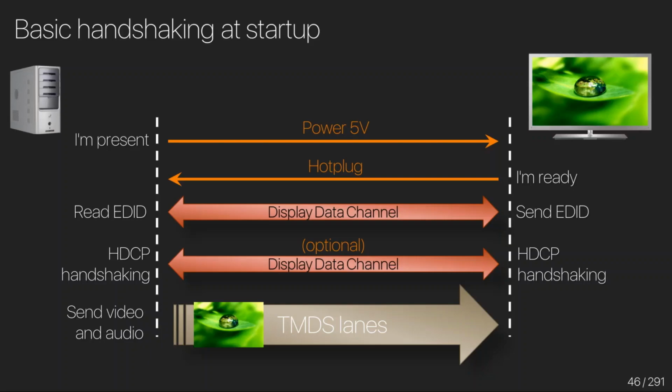So a lot of times what happens when you plug your laptop in to another display is the screen on your laptop goes black and then comes back again. And you can see that's when the EDID is being read. It can be quite a useful troubleshooting device because if you plug in your laptop and the screen doesn't go black, that means the EDID is not being read,